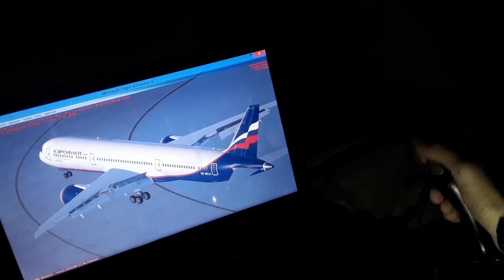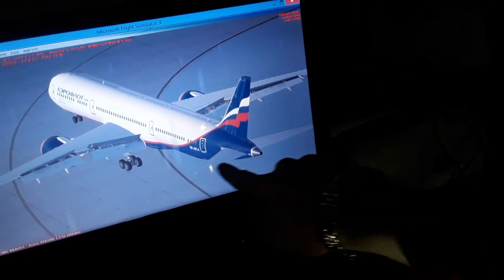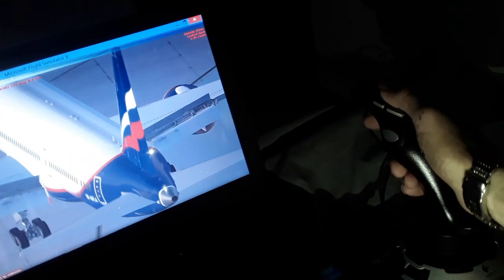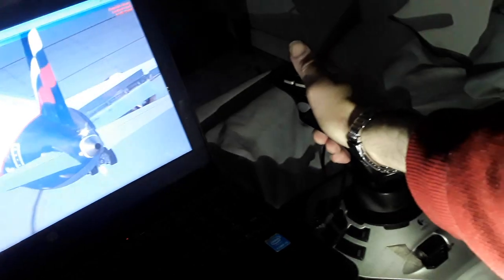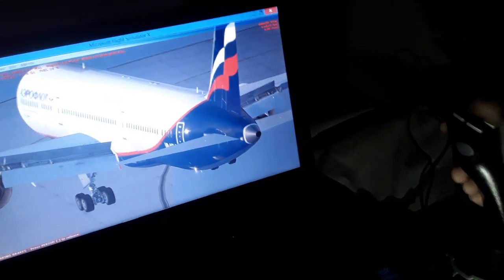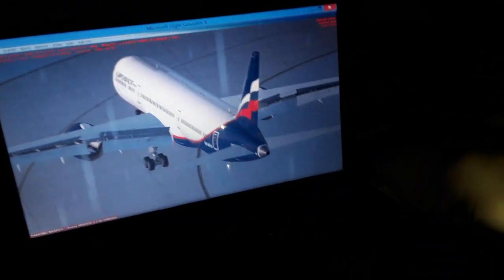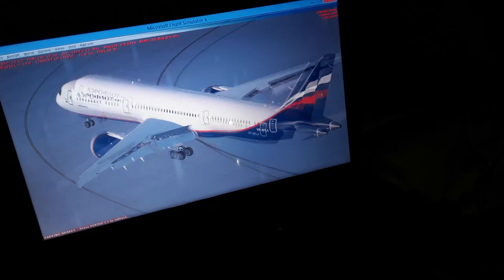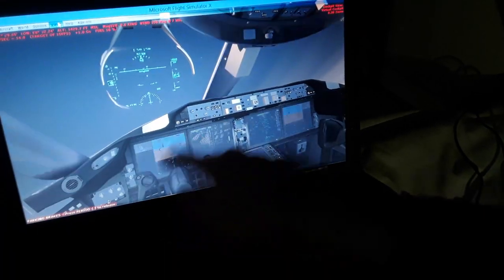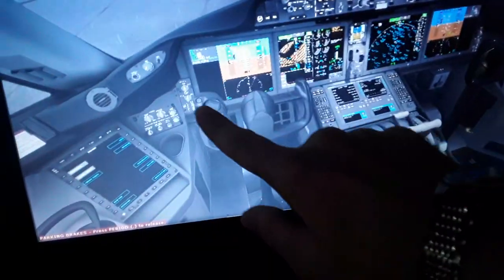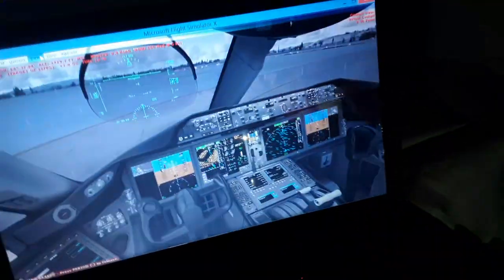We also have, as you can see, the horizontal trim stabilizer. For the horizontal stabilizer of the elevator, as we fly, we can also trim using this trim switch over here, and this will move the aircraft elevator or horizontal stabilizer up and down as we fly to balance the aircraft. So use this trim switch to trim the horizontal elevator of the aircraft. I will show you in a couple of minutes.